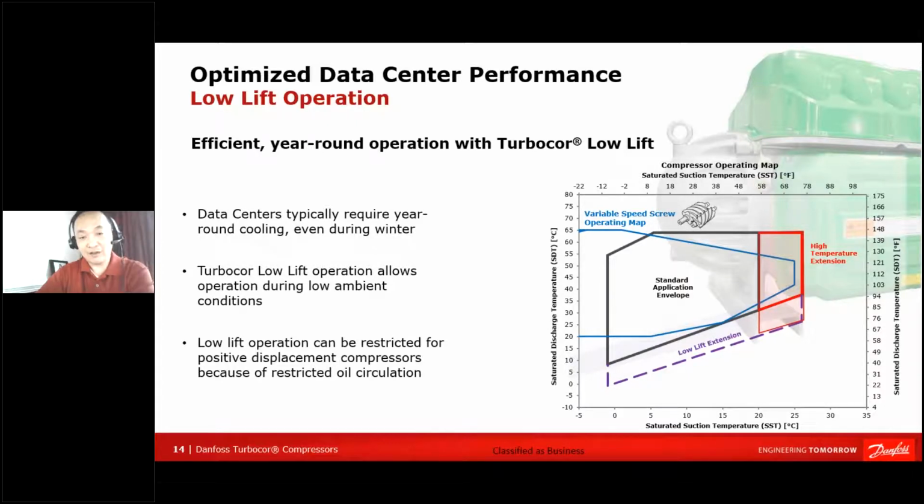Now, for some compression technologies, typically an oiled screw compressor, that can represent some challenges. The reason is that this type of compressor requires a minimum amount of lift to ensure proper oil circulation. Considering that most oil compressors do not have an oil pump, they need a minimum pressure differential to ensure oil circulates throughout the system. Because oil-free compressors do not have oil in the system, that type of situation is not a concern for us.